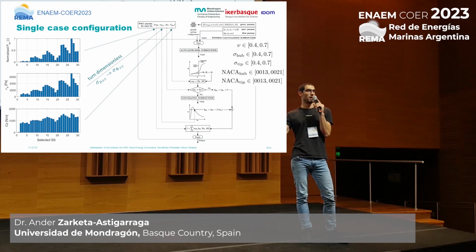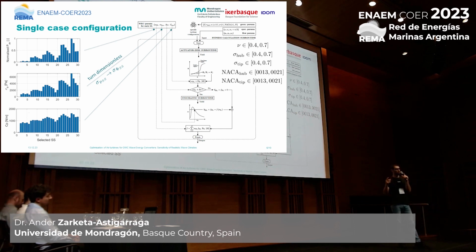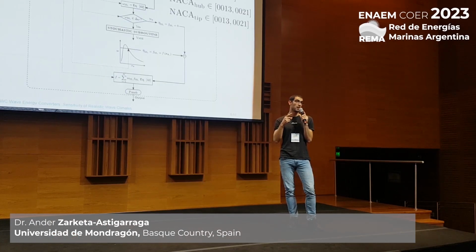That constraint comes from the client side. If you are running at a really high rotational speed, first you have structural issues, vibrations and so on. And second, from the fluidic part, you can have compressibility effects. And if you have compressibility effects and shock waves, that means that the equations are not elliptic anymore, they are parabolic, and you can transmit information not just downwards, but upwards, and you can affect your chamber. That invalidates all the analysis we are doing here. That's why.